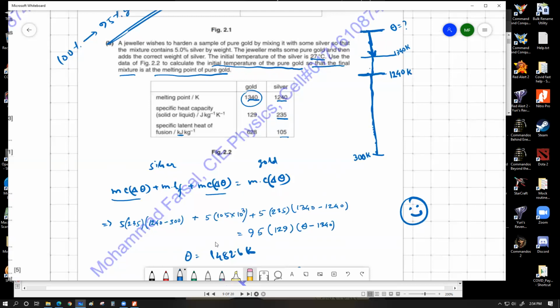So once you build up the equation, the rest of the part is actually very simple. But building up this equation part by part actually can be slightly difficult. And that's one other thing that is important, is that the masses over here were not placed in actual kgs or grams. The masses were placed in terms of percentage. If you wonder why it should work out, because we use all of these equations over here for joule per kg, and over here these are all kilojoule per kg.